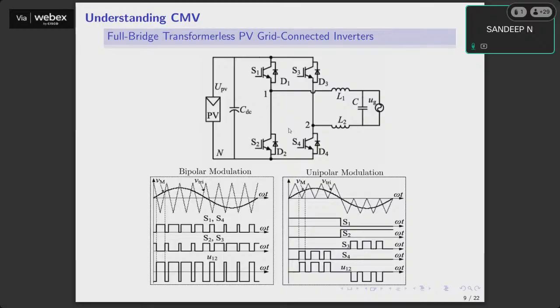So with this on and off we are trying to generate a sinusoid, which is very smoothly varying, and this can never happen, right? Using a discrete function, we cannot build a continuous function. So what we do instead is try to have a sinusoidal function not on an instantaneous basis, but on an average basis.